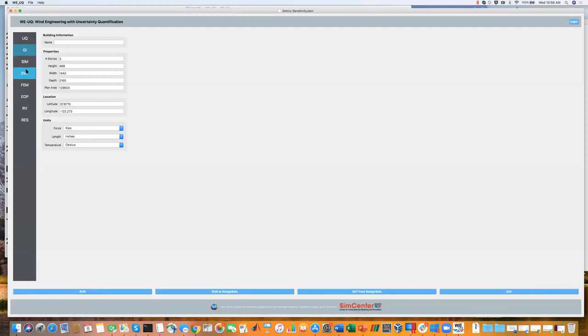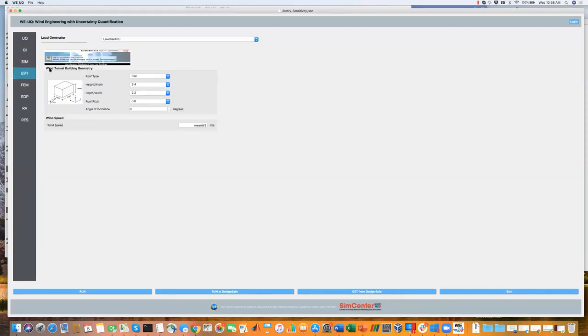Yes, in the sense that you can put in an OpenSees model for whatever your building looks like, but when you come to the events, most of these are limited to rectangular or block structures. If you have your own wind tunnel data, or if you knew what the time varying forces were at the different floors, you could add it as what's called an existing SimCenter event.